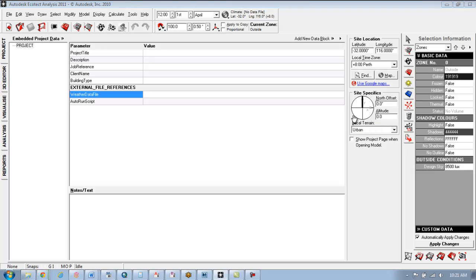By default, north is up. Once we actually have a model, we'll go through and show how you can tweak it. But if, let's say, your building was on a slight rotation from the cardinal points, instead of trying to model at a 17-degree angle, you can just flip this, and it'll tweak the building even though it'll still line up for modeling.